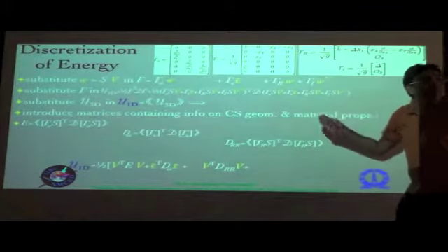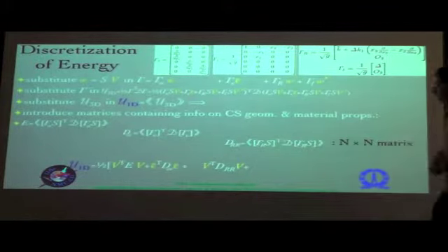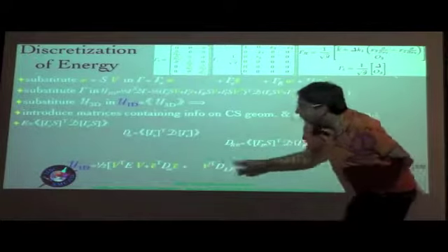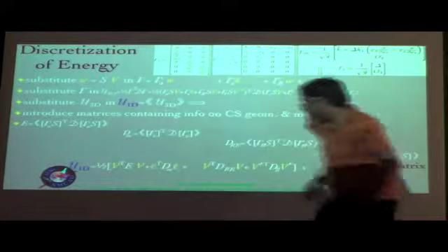So if you had a prismatic beam, this would go to 0. So this is an n by n matrix that you have here, and of course the corresponding term is again V transpose V, very similar to this.